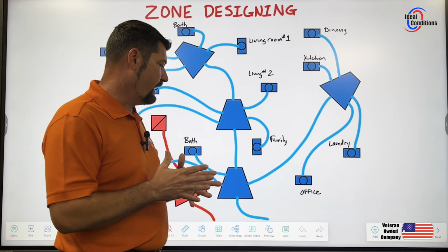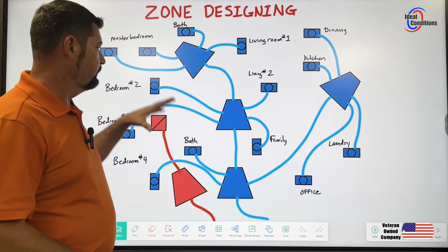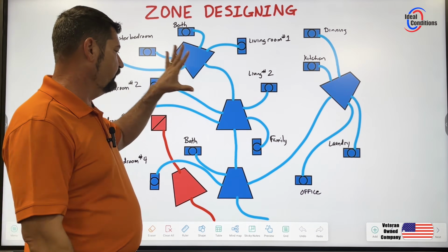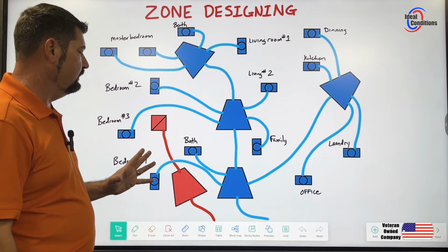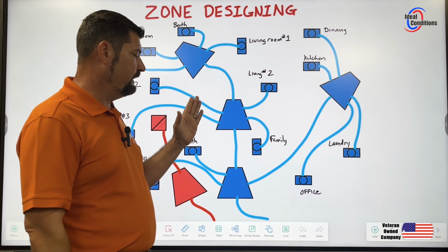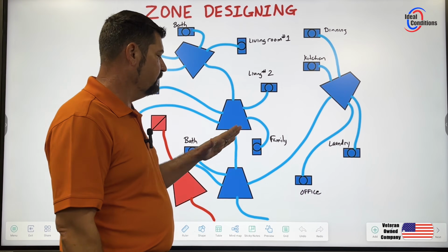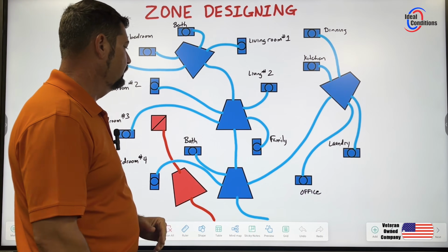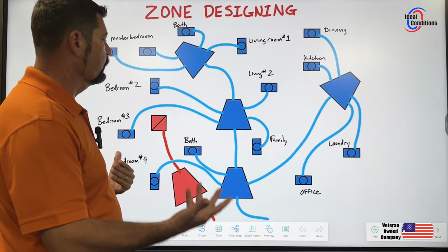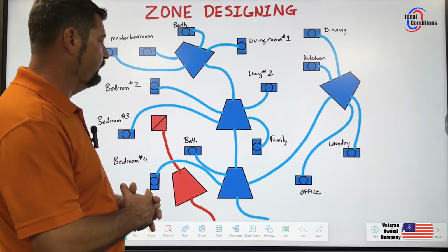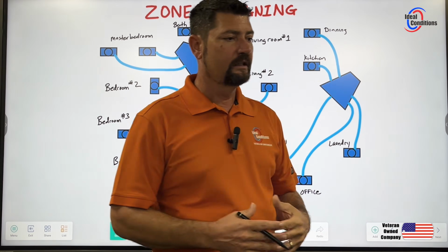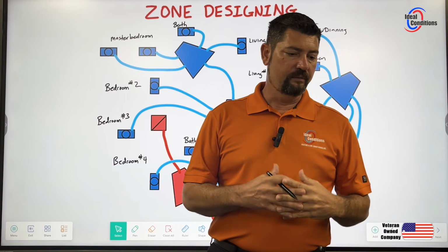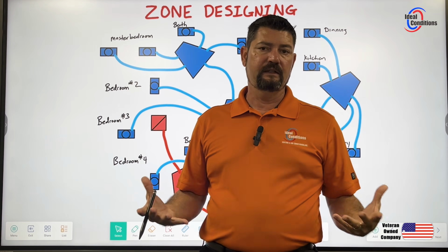And so we have to get into rearranging these takeoffs, adding a mixing box or taking a mixing box away if needed, and making sure that we're putting supply air dampers on trunk lines so it can work correctly. So the first thing we need to do is find out how many CFMs we have, because when we're calculating damper sizes, we're calculating it by a trunk line.